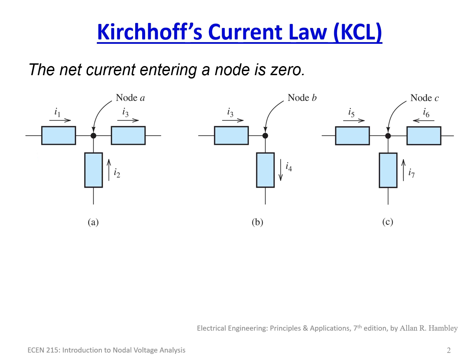So we have 3 circuits here, and we have simply I1, I2, and I3. And since in the node itself, we cannot have any holding of current, the node does not store current. It is just a connection point. That correspondingly means that we can write a set of equations. And so we write that I1 minus I2 plus I3 is equal to 0.